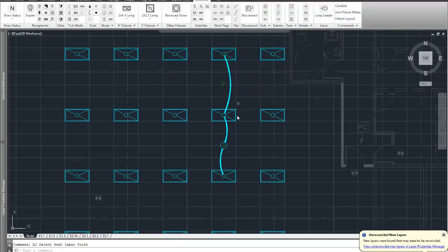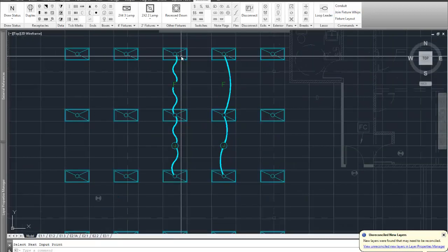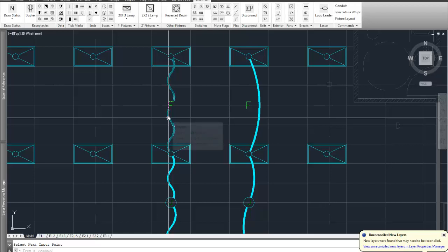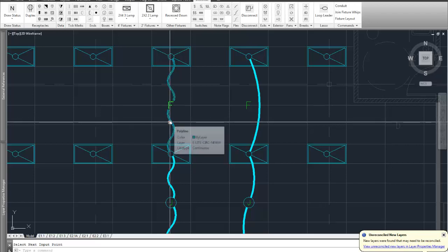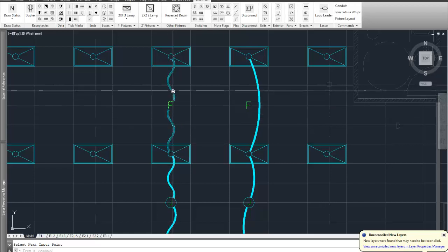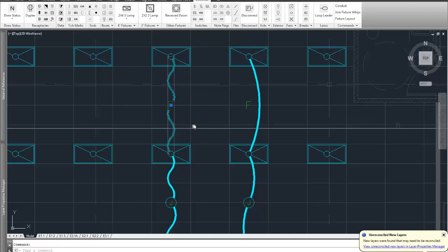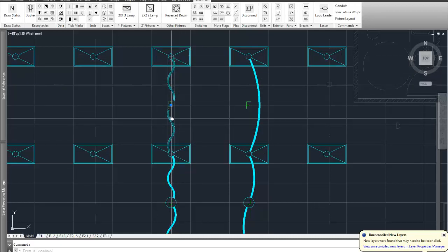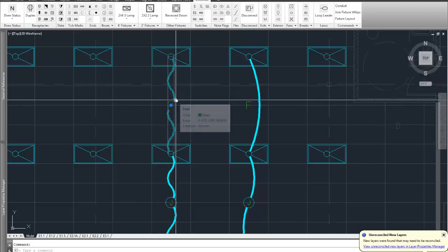Okay. 1, 2, 3. Perfect. Now, if I click on this, and actually as I highlight over it, you can see that the F is also highlighted, and so is the other side. If I click on that, you can see AutoCAD draw a box right there. What's going on here? This is by default a group.